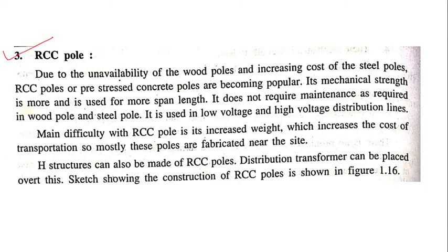Now we are going to see the RCC pole. Due to the unavailability of wood pole and the increasing cost of the steel poles, because steel is very costly and the rusting problem is still there, and in wood the moisture problem is still there, so we are going to use the RCC pole, and pre-stressed concrete poles have become more popular.